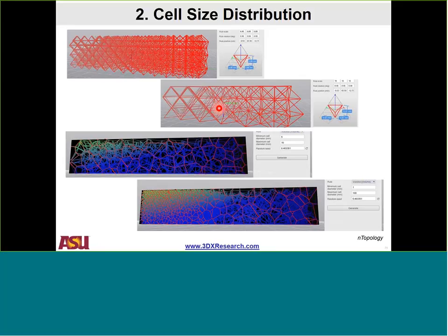If you go with a stochastic structure, it becomes a little more challenging to decide how you're going to make these choices on distributing your cell size. But the nice thing is you get much more freedom. When you have a regular structure, it's difficult to make all the regular structures fit in unless they're identical. When you take a stochastic geometry, software allows you to do that fit. So this is what we call a Voronoi tessellation, and it looks like soap bubbles because it's that similar idea of filling up space.